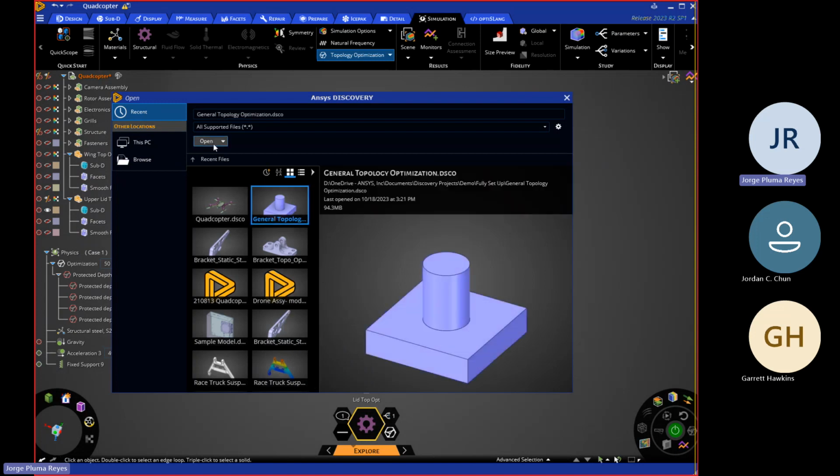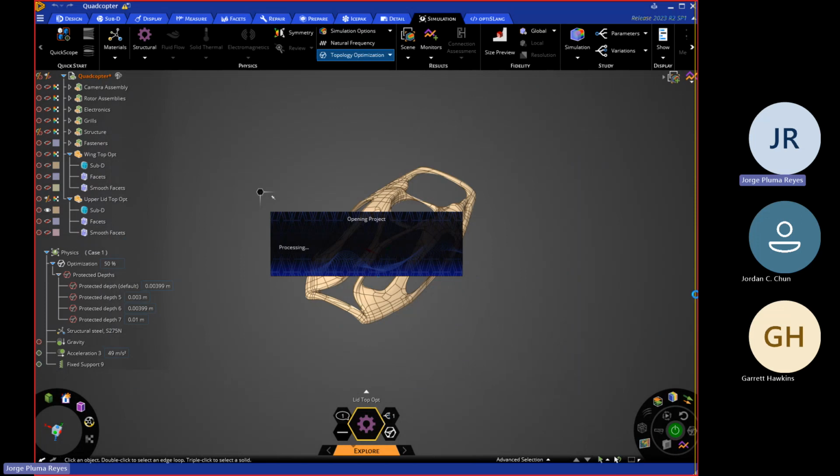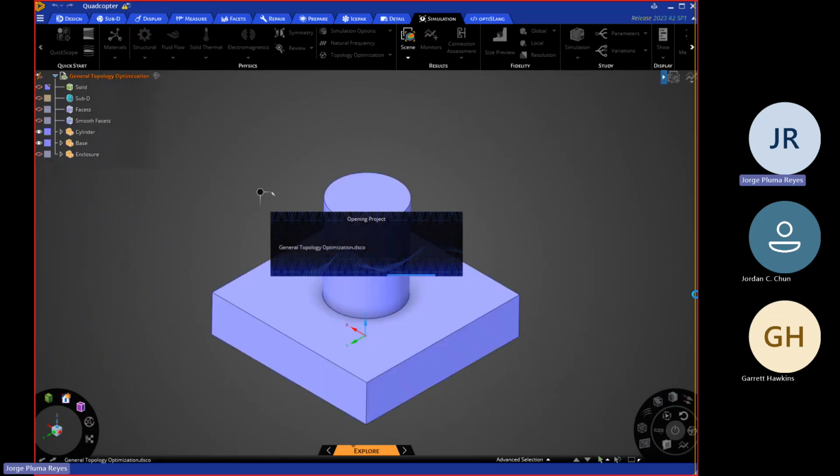Let me open this guy up again. And I'll end with this tip, but pretty much what you can do is, if I wanted to optimize this body, for example, I wouldn't start from here if I have the chance to add more material. So what I would do is create a bigger chunk of material and allow the software to have more material to chew on and kind of eat away.